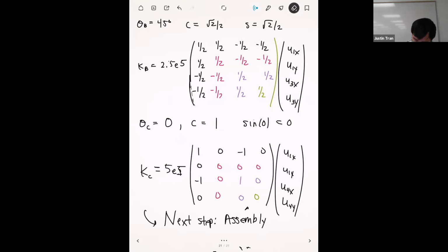All right. And so this is where it's going to be a little bit hard to keep track of everything, just because we have 8 total unknowns here, right? So 4 nodes. At each of the 4 nodes, we have two components of deformation. And so our global assembly matrix here is going to be an 8 by 8. All right. Any questions on this?